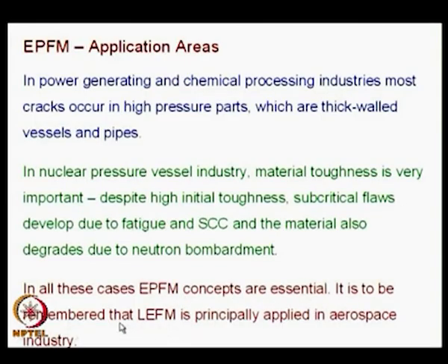It is to be remembered that LEFM is principally applied in aerospace industry. So, the application areas are different. LEFM is confined to thin structures, what you come across in aerospace. When you have very thick material and highly tough materials, you have to go in for J. And I had also mentioned long time back that K1C determination fails for a nuclear reactor steel material, because if you determine the thickness, a person can sit on it.